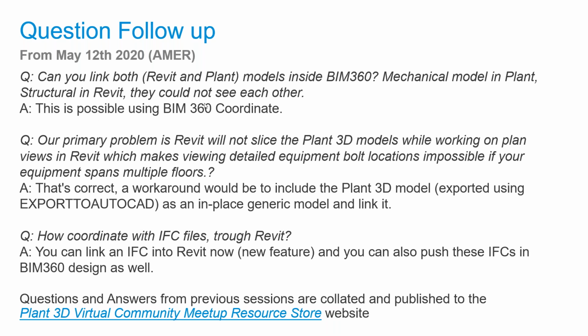There was a question about, can you link both Revit and Plant models inside BIM 360? The mechanical model is being done in Plant and the structural model in Revit. In the past, this person could not see them together. With BIM 360 Coordinate, you have the ability to work with DWG files and Revit files, and I believe IFC files as well. You can use those with BIM 360 Coordinate to actually do clash detection.